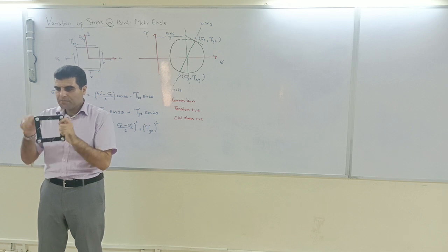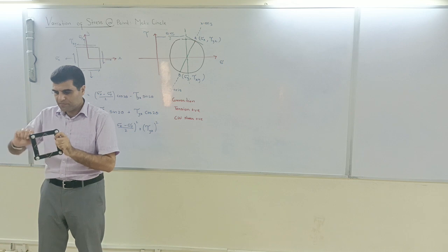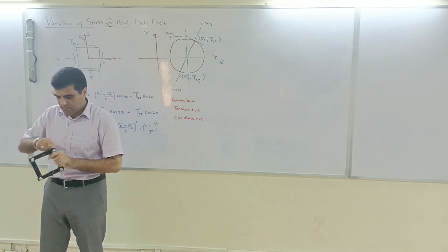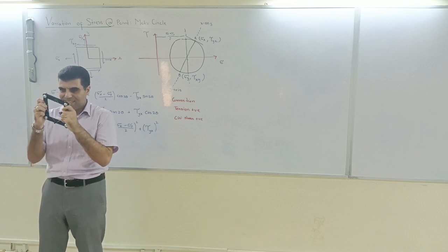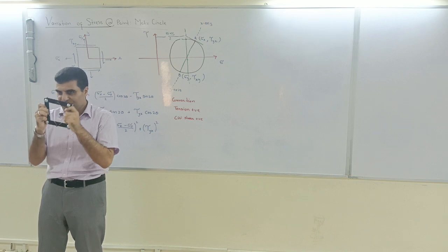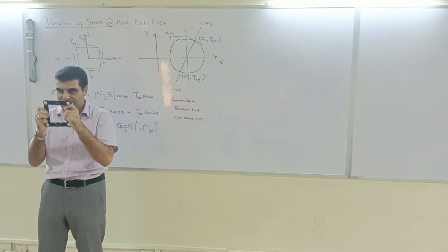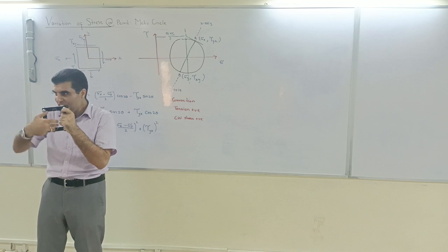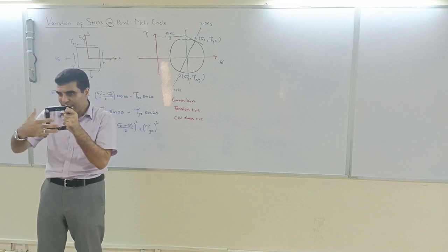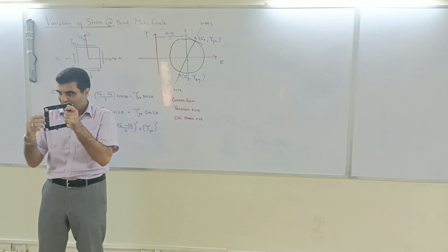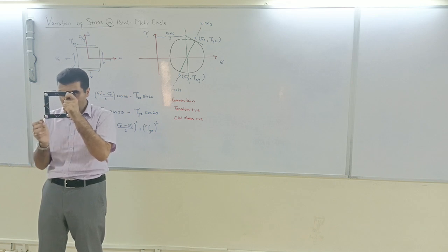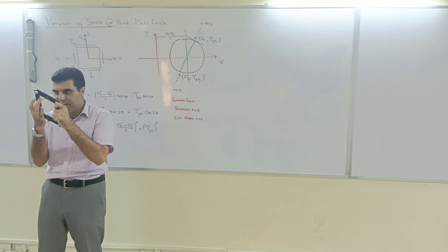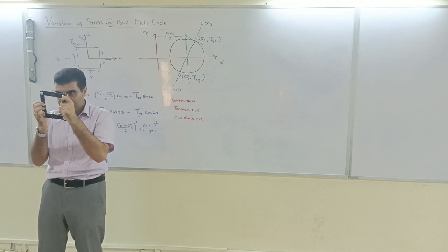When I draw this, this is the shear, isn't it? Only shear. So what's happening? You have another box where you have principal stresses, only axial. See? Only axial. This was initially a box. It stays like a box. So there is no shear in this rubber band. Look at the rubber band.